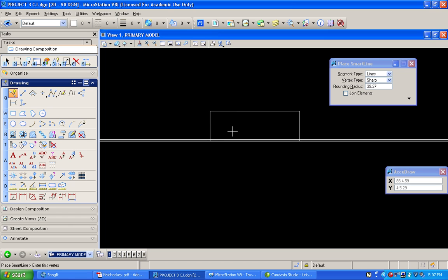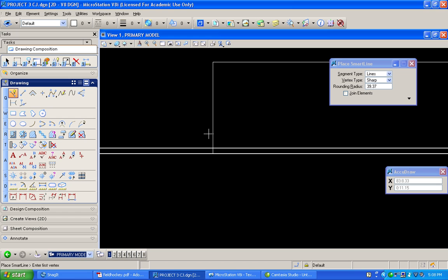I'm going to do the same thing on the other side. Actually, let's be lazy. Take this, grab the piece we just drew. We're going to do a mirror again. 3.5 is mirror. Change it to vertical and click on Make Copy. And we know we can snap to this center point. In other words, when you're mirroring something off a center axis, it's going to spread it the same distance in both directions. So if I just left click on this center point, there's our goal location.